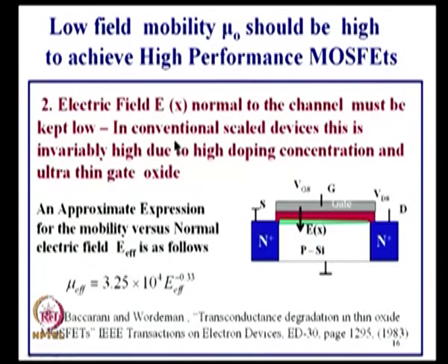But you know, when you make the oxide thickness small and the channel doping high, when you deplete the channel, there will be a very high electric field. Oxide thickness is small, the depletion layer charge is high. So, QD by C oxide is the electric field, okay, or whatever charge is there, that gives rise to the electric field. QD by epsilon oxide, that is the electric field.